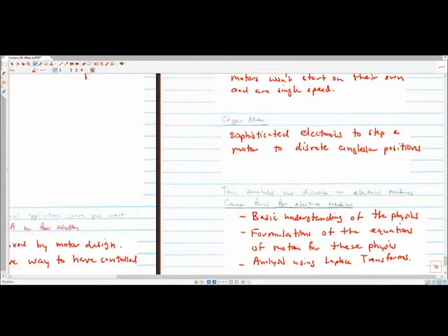Yes? For AC synchronous motors, how do you get them started? I think I've used them before, and they have like a big capacitor on the side. Yeah, so they have motor starters. Some of them actually have a separate motor that will start them. The other thing you can do is stack them also with a bunch of conducting metal, and that mutes the poles of these, and so allows you to then get them started. So the video, we can go back and watch the video.